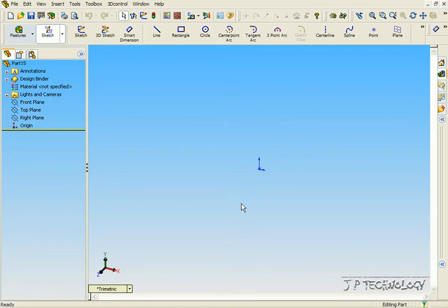So we're going to be covering the traction wheel on edge feature, and what this is going to resemble is a wheel and an edge moving together like a rack and pinion. So you'd use this kind of like to mock up a rack and pinion that you're developing and just to see the motion and how it's going to move together. Again, we're going to be using sketch blocks.